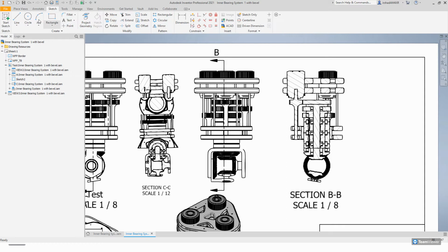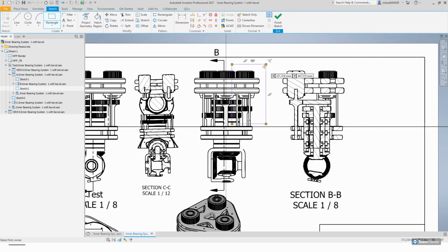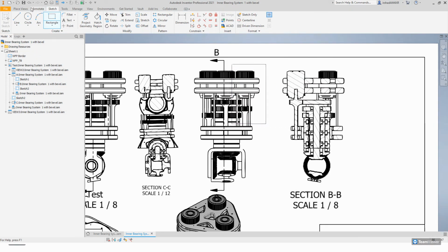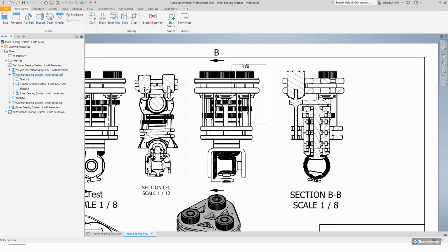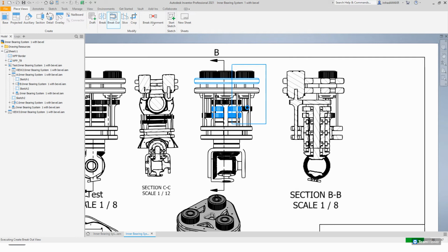Well, you've got to draw your closed view first. So I'm going to go here, and I'll say finish sketch. And now that we have a closed loop, we can say, I want a breakout view from, I can choose a point on any of them, or I can choose to sketch to hole through part. And I can say there, there, there, there. Okay.